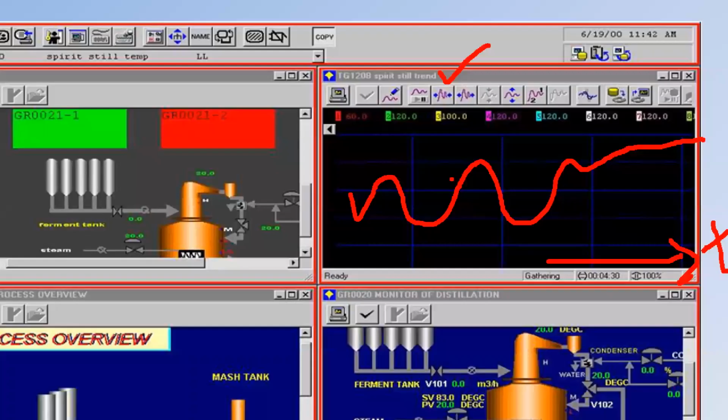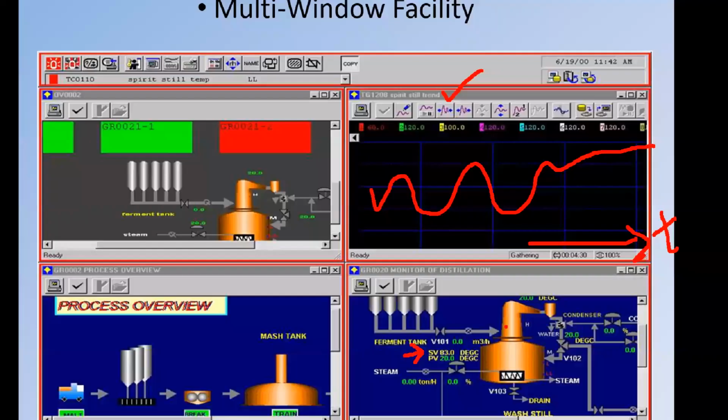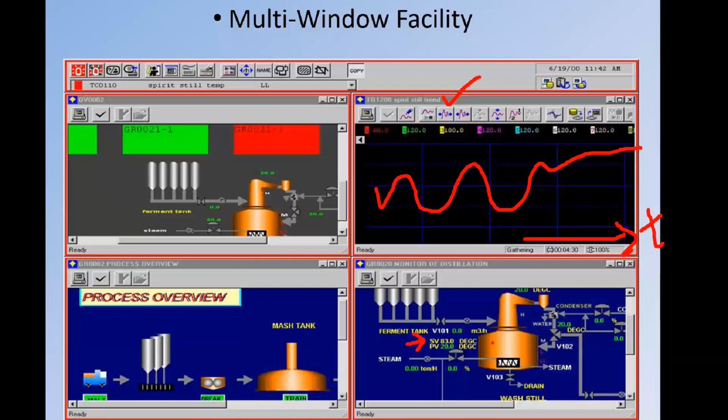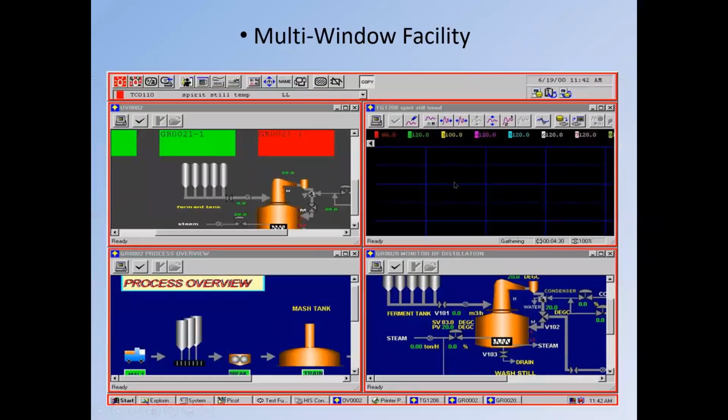Means what is the pressure, temperature, what is the set point. You can see here set value, process value. All these values, temperature, pressure, flow, you can monitor on a screen itself. You don't need to go and check the programs to see the value of this. You can directly see it on a screen. Correct? So this is how you can reduce the human effort using SCADA graphics. We will build one SCADA in a few moments, and we will try to indicate our parameters using PLC programming. It is a very easy thing.